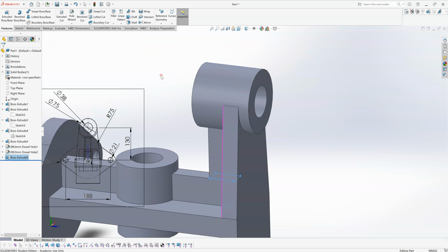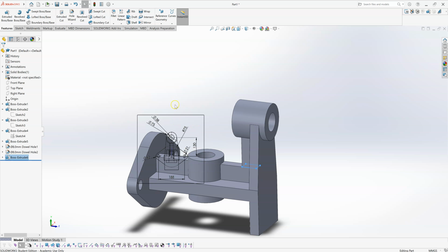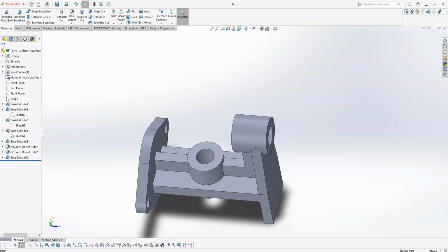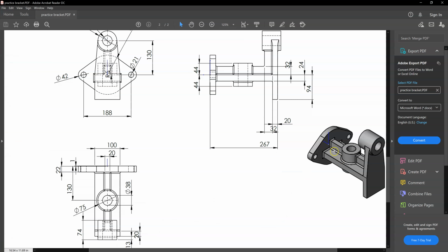Okay, and I think that then is all the geometry done except for the fillets. I'm going to delete this sketch out of here, and I will go along then and fillet. I think it's basically all of the intersections between that inverted T-shaped web and the other features. Also, there are fillets at the intersection between this vertical face and this cylindrical boss as well.